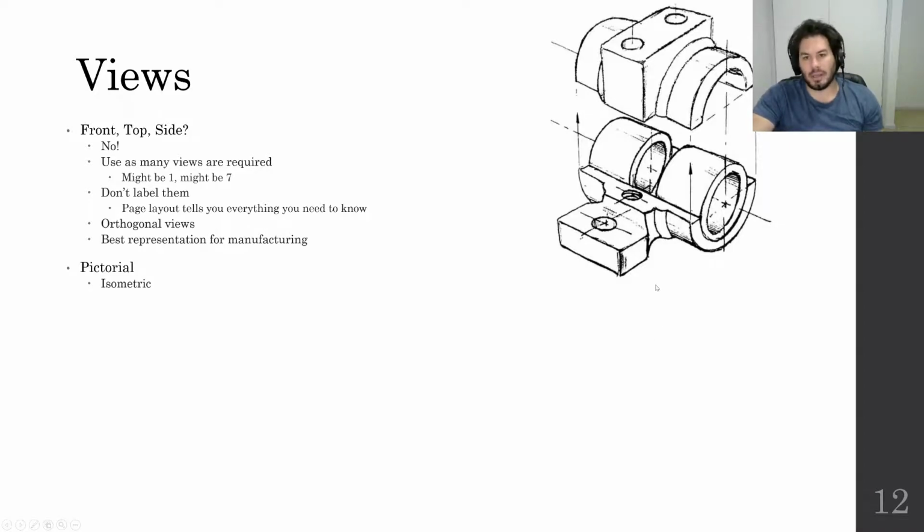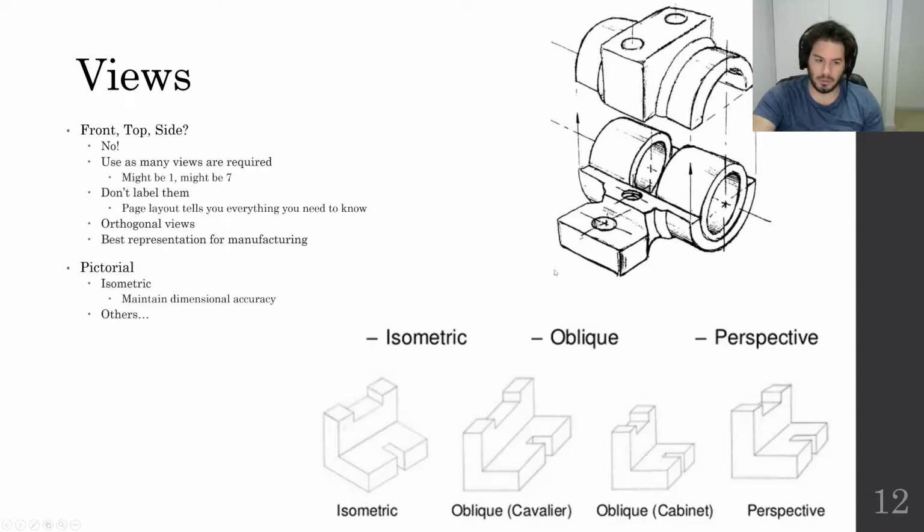The most common in engineering by a mile is isometric, and it's really the only one that's worth knowing, but there are others. This is an isometric view. Isometric is good because it's ISO, one metric measurement, meaning this object, you could put your ruler on any one of these vertical lines, or any one of those lines, or those lines, and measure it, and it would be correct. So you draw everything to the same ratios. Again, really good for engineering applications where exact dimensional accuracy is important.